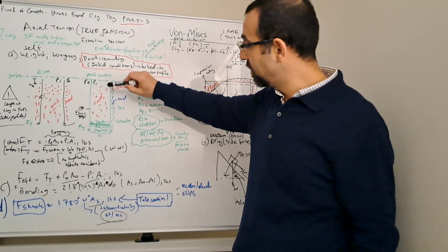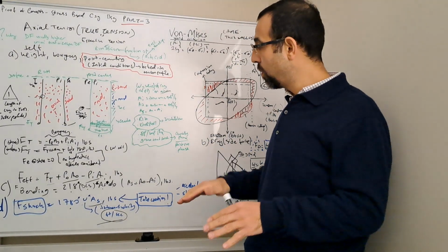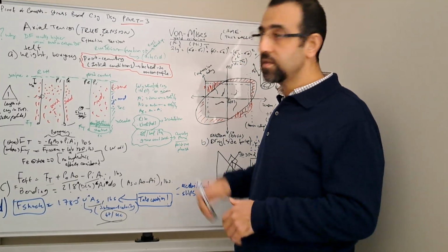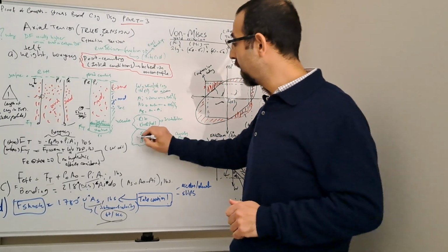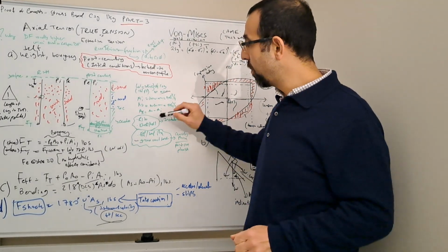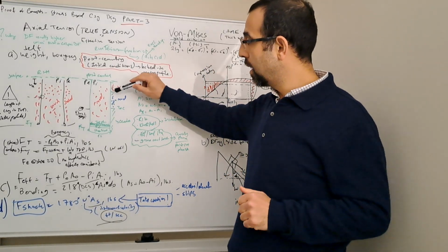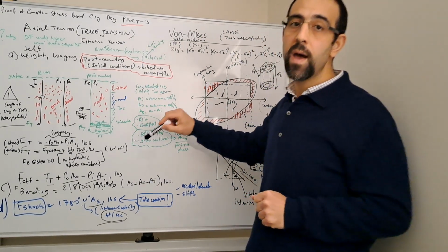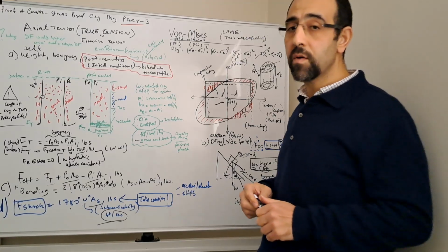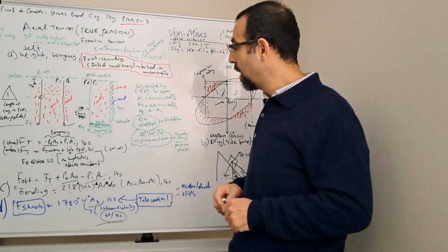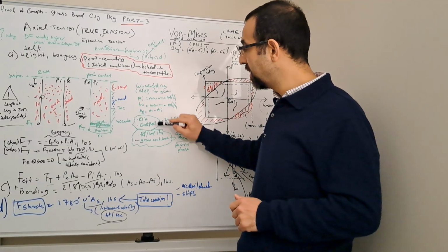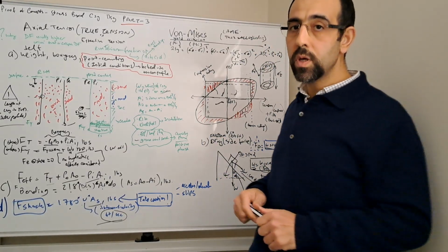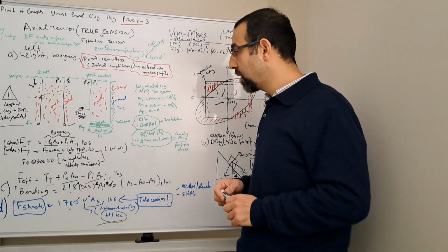Then we bump the plug with the FCP plus 500 usually, and then we take the pressure up to our green cement test value, maybe to some pre-agreed pressure. That's going to have a significant effect on our axial tension profile, and the same goes for the pressure test later on.